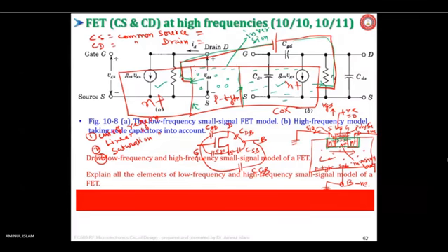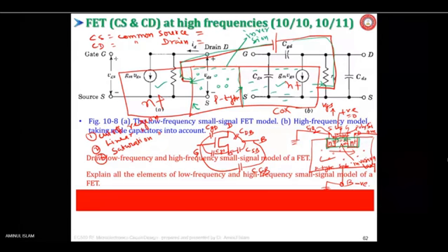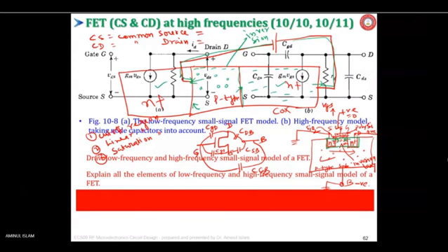My question was how these electrons are coming. I asked from where the inversion layer electrons are coming. You said yes, it's coming from the N plus region of the N MOSFET, the drain or source diffusion region. One side is drain, the other side is source. From the diffusion regions it is moving. That is your answer. Now my question is, is it possible that it is moving?